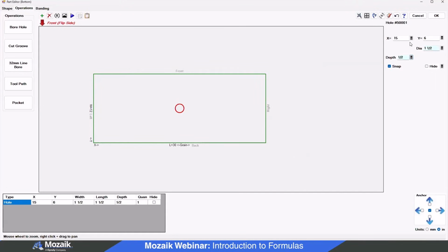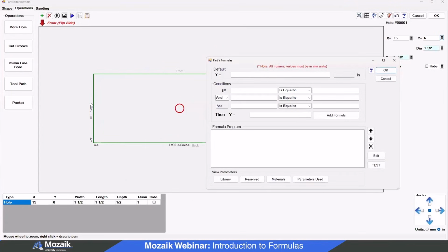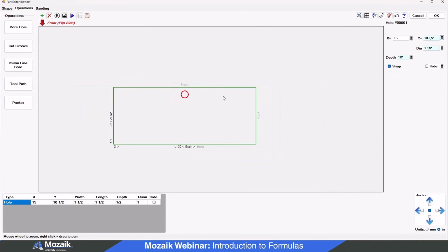Now my Y, similar to those light strips, we're going to go across the width of the part. So that part width, so the W, the L, I'm going to use the part W. So we're going to say part W minus puck light width. And we'll say, okay. So with that formula, it's from the front to the center of the light.